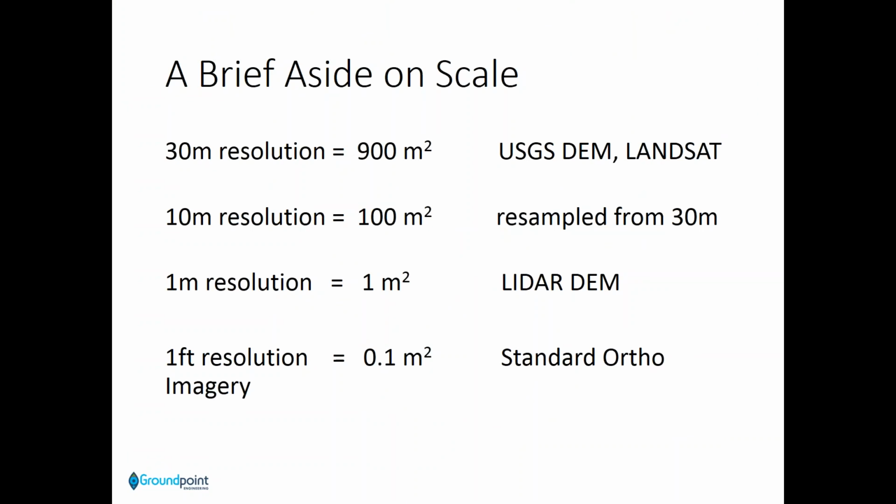But using standard 4-band ortho imagery and LiDAR, we now have the ability to create land cover and hence curve numbers at 1 meter resolution. So we came in saying, hey, I think we can do better. We think we can adapt this Cornell model to the real world and apply it using much higher resolution data.